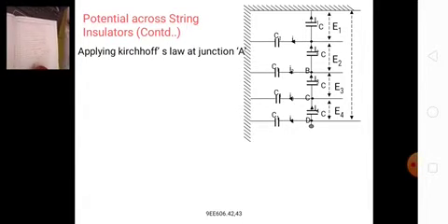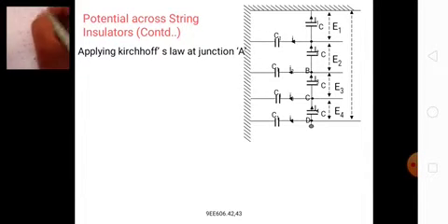So that is equal to E1 into 3 by M plus 1 plus 1 by M square. So multiply and divide with M. So that is E3 is equal to E1 into 1 plus 3 by M plus 1 by M square. And the voltage across the conductor, IC is equal to E1 plus E2 plus E3.